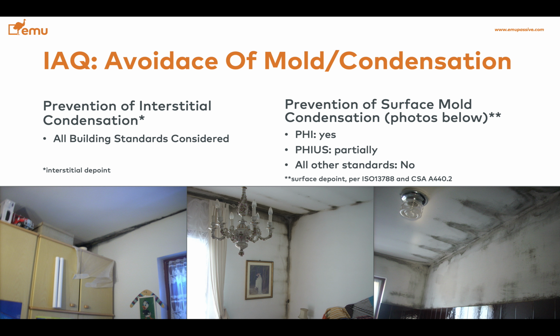PHI has hard requirements for this, in that they require ISO 13788. Fuse partially. Fuse also accepts other condensation verification methods such as the NFRC condensation resistance and the AAMA 1503 methods, which are not really that strict in avoiding surface mold and condensation.